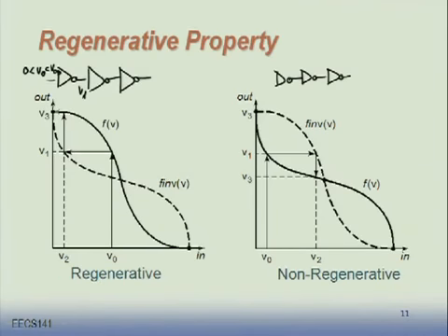Now, what is the voltage transfer characteristic of the second inverter? Well, I can overlay it on top of this one, right? Now my input becomes the y-axis. V1 is the input to it. The x-axis becomes the output, so I can overlay the output axis over the x-axis.